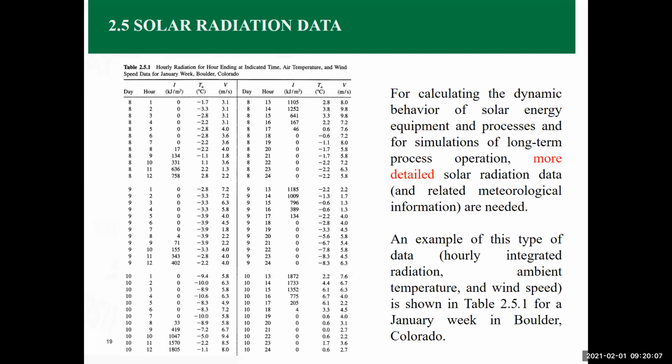If you need to make your system based on 50 degrees, then you are oversizing the unit, and you would be paying a higher capital cost, which is the cost of the device and installation, and you are paying higher running costs because of the cost of electricity for a bigger compressor. Or you may go for the norm, which is like 45 degrees centigrade. You are going to pay less, but you may be suffering just for a few hours maybe every year or every other year. So having the data available is going to help you make your decision regarding this issue.